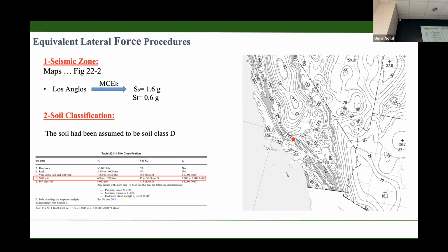You will go into the standards here. This is the standard, and we're not going to use it. I'm going to tell you something else if you don't have the standards. So this is ASCE 7-16. There's another one, it's ASCE 7-22, and then there's a figure, I believe it's a 22 something, like seismic maps here. And this map tells you what is the seismicity of each state and location, like a contour map. So for example, here, like Florida, and then you have here California. So you have all the seismic maps here.